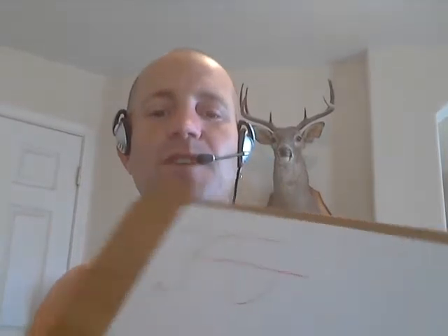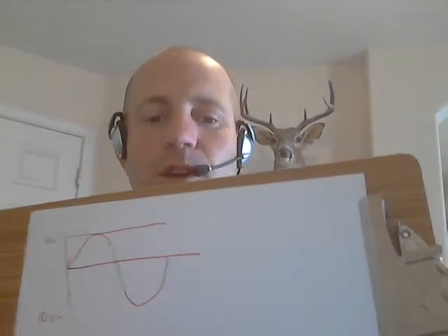But as it begins to spin and moves another 90 degrees, it's going to be perpendicular to the magnetic lines of force, so it's going to be cutting through them at a relatively rapid rate, and thus it's going to generate its maximum voltage. Okay, so our AC signal may look something like this wavy line that I've drawn.